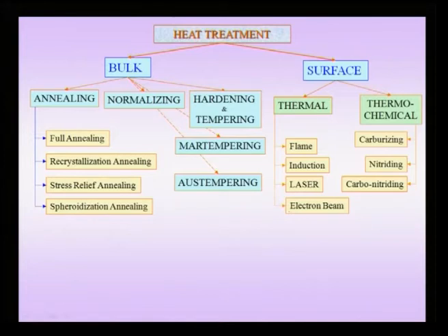The general superset is that we can have either thermal treatments, which are called heat treatments, or thermomechanical treatments. In thermomechanical treatments, not only do you apply heat, but you also additionally work the specimen, maybe at high temperatures, so that you can get a certain microstructure which is very desired for the properties.